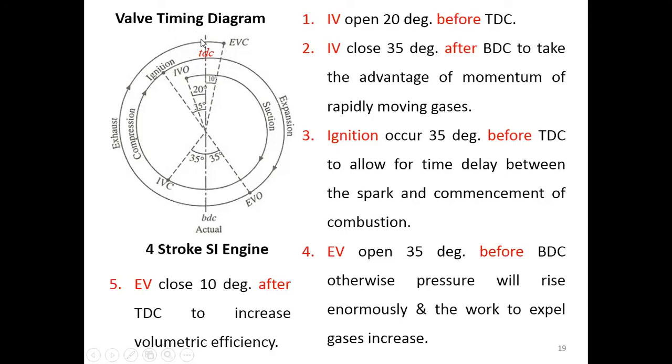This is the ideal position for the maximum pressure to happen. But unfortunately, we rarely have this. We normally have the maximum pressure happen after the top dead center, if you remember the event that I showed you. Okay, so ignition happens here, and then after that combustion, and then expansion.